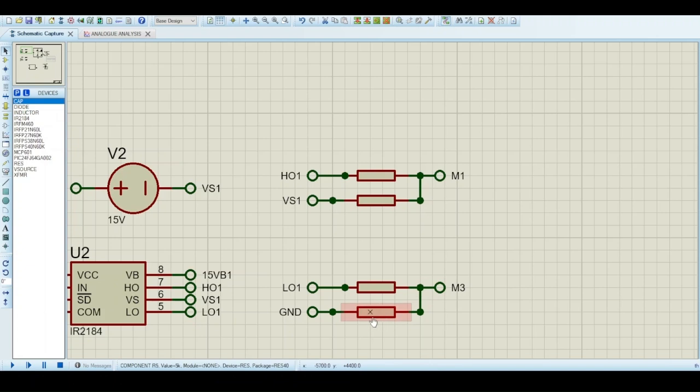The primary responsibility of this resistor, the purpose, let's say, is basically to ensure that the gate of the MOSFET is discharged when you in fact do not want it on. So you want to turn it on and turn it off. So the pull down resistor is to ensure it goes off. By default, it stays low relative to the source. So if I click on that, I just use the value of 5K. You could use 10 kilo ohms there.